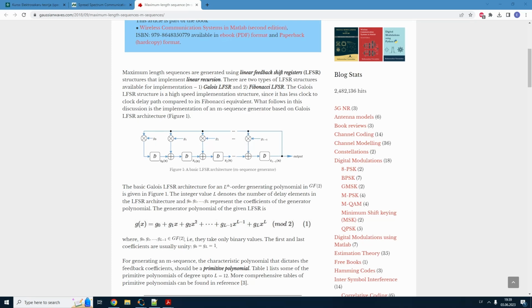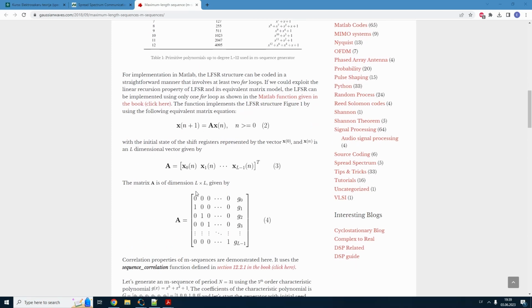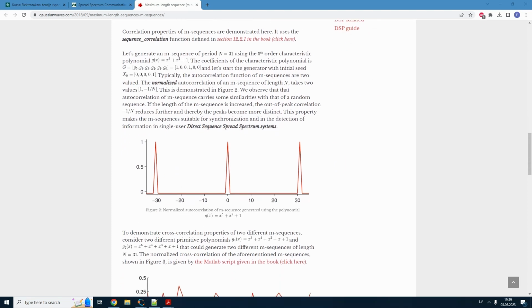Now the good thing about this sequence is that it has remarkable correlation properties. The cross correlation of the sequence with its own copy shifted by different positions leads almost to zero, if it's repeated periodically. And if we have no shift, no mutual lag between these copies of the sequence, then it gives a maximum. It's very similar to what we tried to do with delay detection for the direct feedback equalizer in the previous practical exercise.